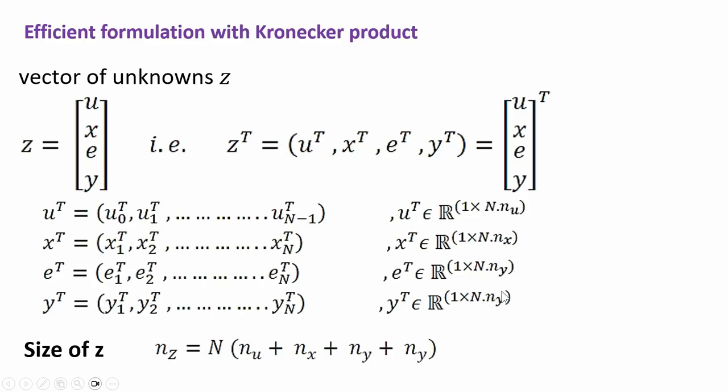Therefore the error between the set points and the output variables to be controlled, which is this e, can also be more than one. So this e can also be a vector, and similarly there can be more than one output in a process. That's why this y can also be a vector. So for a MIMO system with multiple states, all of them in themselves are vectors.